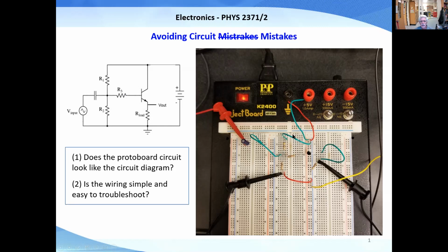That's right here, R3. And then there's this biasing voltage that's added to whatever the input is. There are two resistors here that are vertical, like they are here. And then the capacitor on the left is there to block any DC voltage coming into the circuit.